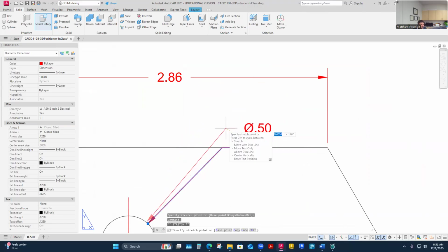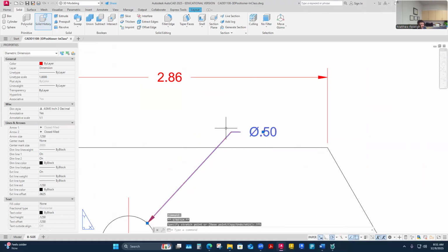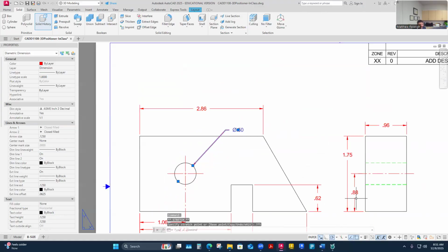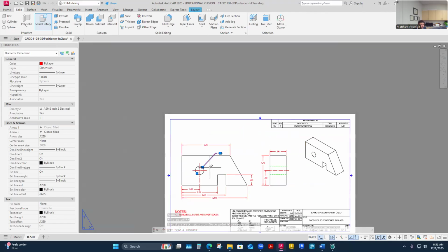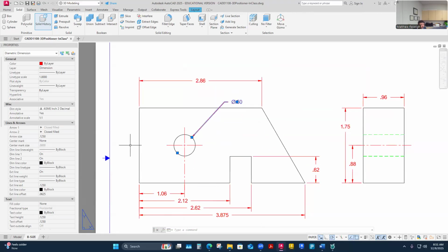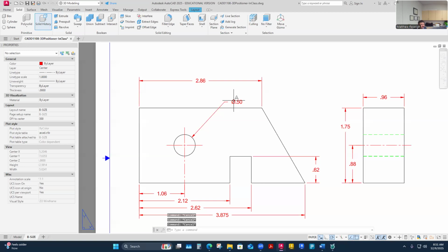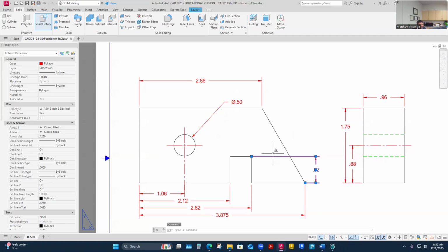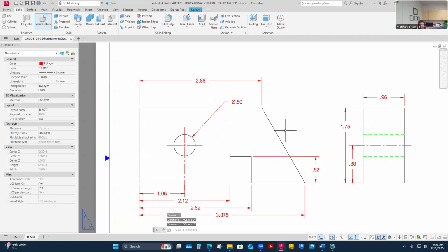You did locate the higher proportions from the. Yeah, this side I went over here. Either side, you could. I probably wouldn't pull it here because that's not in between the 2 views. Yeah. Generally I do that too. Generally my size and my location will be with the size dimension. But this, I broke my own rules just so I eliminated a long extension line. But I have this long extension line, so it really doesn't matter that much.